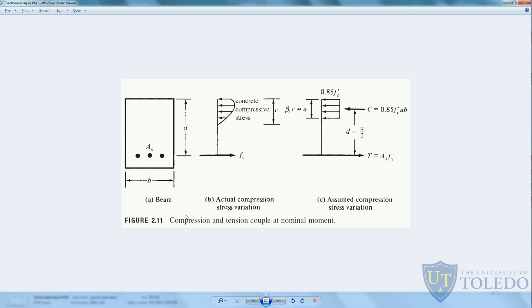Response 2000 basically performs a sectional analysis of a reinforced concrete cross-section that the user defines. However, differently from the hand calculation sectional analysis that we do based on reinforced concrete codes such as ACI 318 or AASHTO, Response 2000 takes into consideration the nonlinear behavior of both the steel and the concrete in the cross-section.